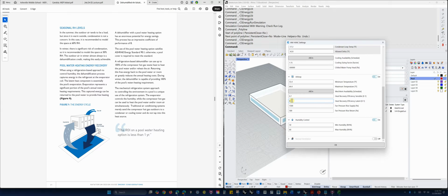energy recovery to 0 because in the specifications we do not want to ever be bringing in extra humidity, which could happen at certain times of year with energy recovery ventilation. So that's why this is 0. This 0.7 means that 70% of the heat in the air, well, if it's cold outside and we're bringing in fresh air and taking our nice warm air inside and exchanging it with that fresh air, we are exchanging 70% of the heat with this. So we could go higher than that 70. That's pretty conservative. There's equipment that will go higher, but that's what I'm going to leave it at.